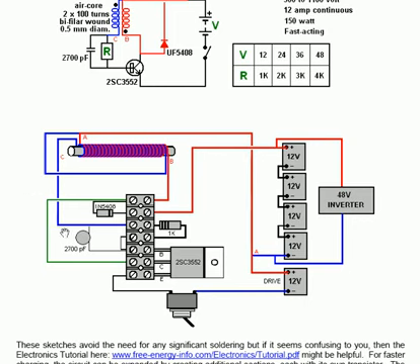If you don't get the smallest one, you may find that the transistor pins, which don't bend easily, are not the right spacing for these connectors. You get around that by bending the central pin vertically up in the air and using one of these cut-off pieces to screw to that, and the wire from that then goes to, in this instance, this connector over here.